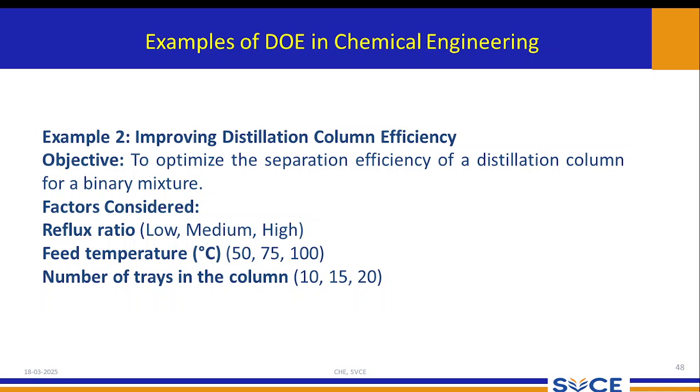What is the effect of feed temperature? As you increase the temperature, what is happening? It will get easily vaporized. Okay, it's a flash vaporization. For example, I set the feed temperature at 90 degrees Celsius for water. What will happen? Obviously, the water will become vaporized, right? Because it is going to attain its saturation temperature. Like that, like methanol.